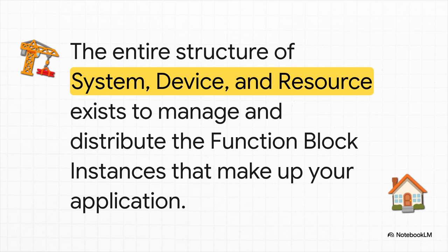System, device, resource, all of it exists for just one reason: to give your function block instances a place to live and run. It's the framework that lets you take these software building blocks and logically spread them out across all the physical hardware in your factory.